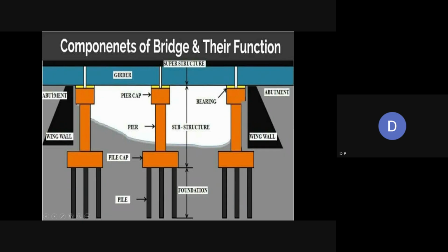The soil or the material is added so that this particular section will be open for the water discharge or to cover the valley. And the abutment will be on the little upper land, and this is done so that economy will be achieved and the span of the bridge will be less.